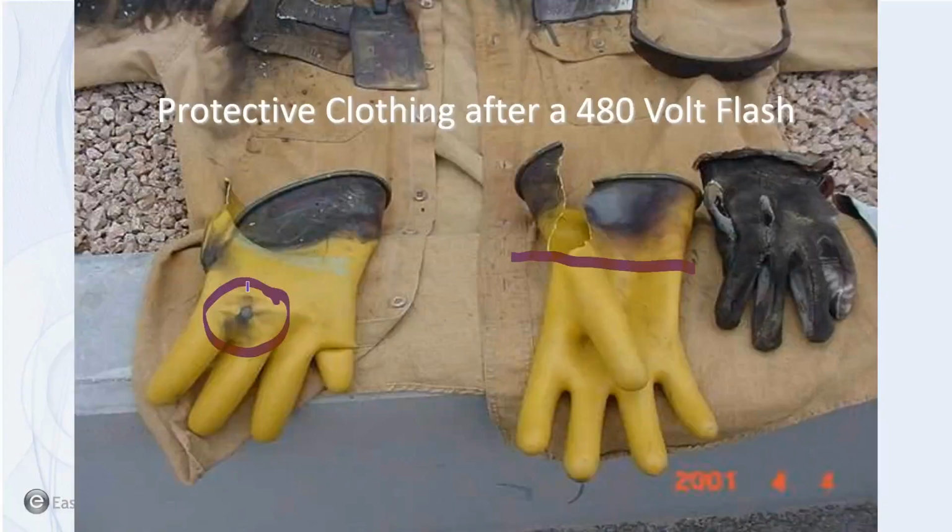Unfortunately, what happened wasn't because of a pinhole. That was because of the ionization of the air in this 480 volt arc flash that caused that ring to heat up and melt the rubber. So this guy had a real significant burn on his ring finger from that event. And so my thought is take all the jewelry off. Don't be wearing anything metal, no metal rim glasses, anything like that, that in an arc flash event would superheat and cause significant burns. It's not going to be a fatality, but it's a burn that's unnecessary if the jewelry had been taken off. So that's just a little sidebar on that one.